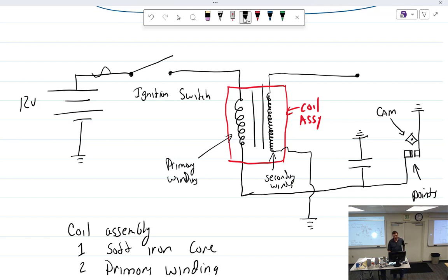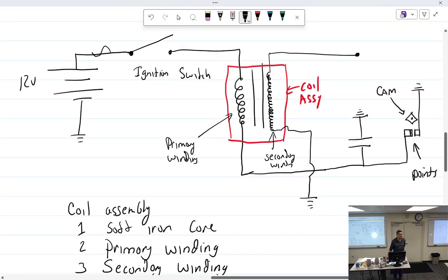By having a coil assembly. A coil assembly is nothing more than a transformer. That's all it is. So we just call it a coil assembly, just like we have over here a capacitor, we call a condenser. Yeah, we just change the names to confuse people. So it's the voltage that's creating the spark. It's not the amount of current it creates. You got it. We don't need much current. Well, we need a couple electrons to bump over. You got to bump them with a lot.